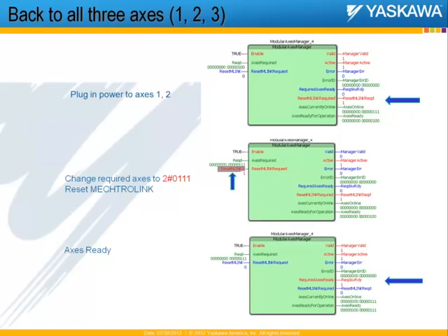Okay, so the question was whether the required axis ready output comes up as a live output or not, or does it require some toggling of input bits. As you can see, this function block that was built is basically built on the PLCopen standard, which means that if that function block is being run off an enable input, and that enable is held high, it will show the live status of what's happening. So it does not have to be toggled. There is no execute bit to toggle. As long as the enable bit is true, it is going to show the live status of your machine.